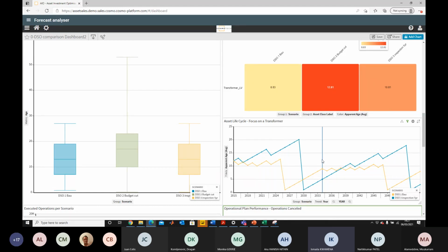However, the only risk associated with this scenario is that, looking here at this case where a replacement was carried out because an inspection was performed here, if we do not perform any inspection at this point, we wouldn't know that there is a need to carry out any replacement. So there is that risk of failure occurring without us knowing, because we did not carry out any inspection. But as I mentioned before, a certain number of failures is acceptable, provided that we have a good redundancy system in place.